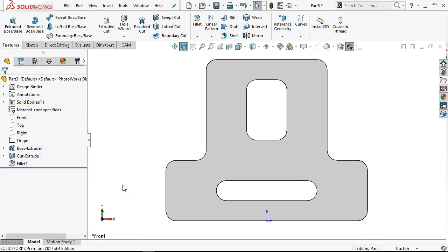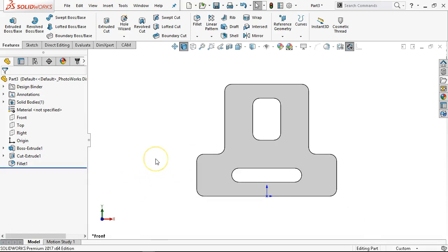All right, so once I have all of the fillets, so what did we have? 4, 6, I didn't see what it said, 16, 18 fillets. That would be sketch fillets that I would have to draw into those sketches at each of those points, rather than just picking one feature command and being able to generate that geometry.